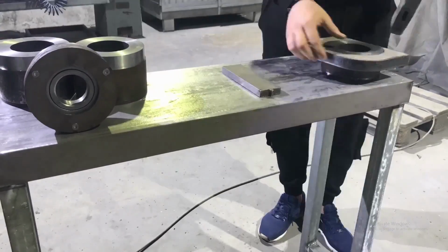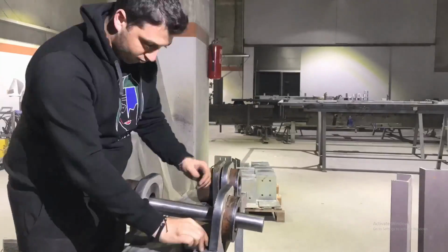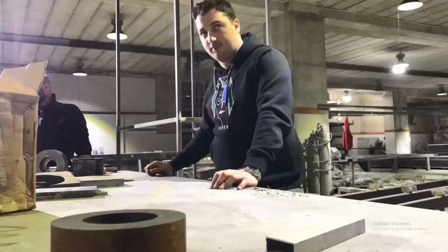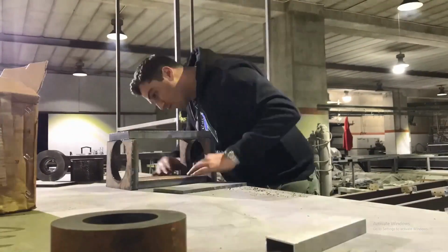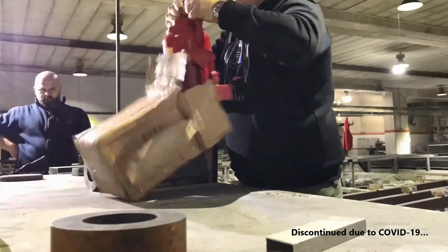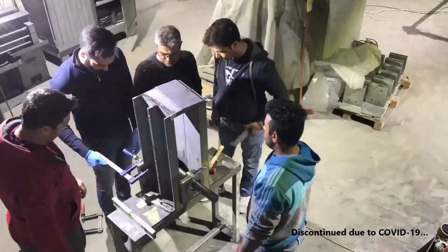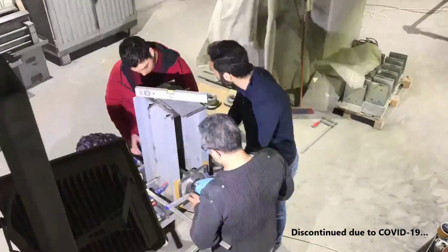Grease was added to the bearings while hydraulically pressing them into their housings. You will now see the slider with the shaft rotating smoothly inside it. Finally, in conclusion, a basic geometry was parametrically designed. This geometry was used for setting up boundary conditions for a simulation to forecast the required force and torque to operate the cold roller bending machine.